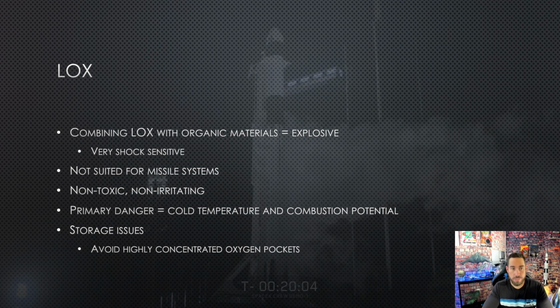It's oxygen, so it's really non-toxic, non-irritating. There are two big hazards that come along with liquid oxygen. Number one is that it's cryogenic, which means it's unbelievably cold, with a boiling point of minus 298 degrees. You have to keep it below that temperature to keep it liquid, which means if you come in contact with it, you're going to have frostbite pretty immediately. You'll have a severe cold temperature burn.